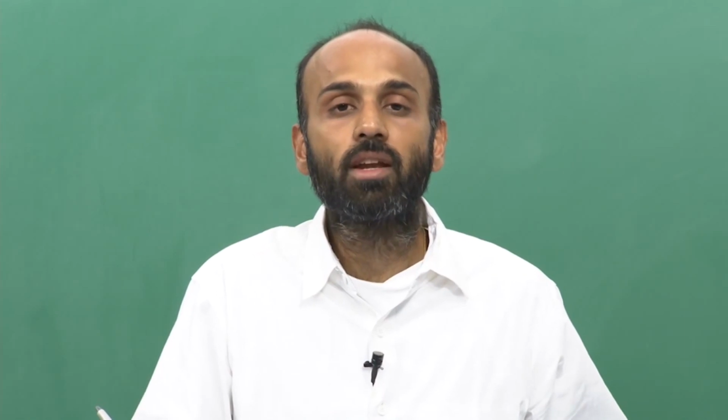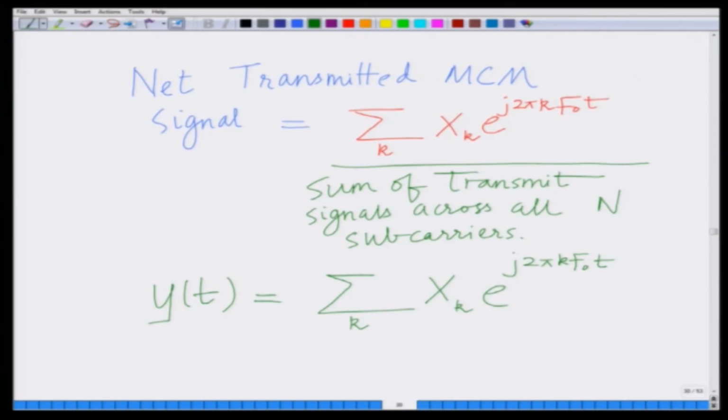Now, how to recover these different symbols? If you look at this expression for the multi-carrier transmitted signal, you will see this is similar to the Fourier series. Notice that this is similar to a Fourier series expansion.